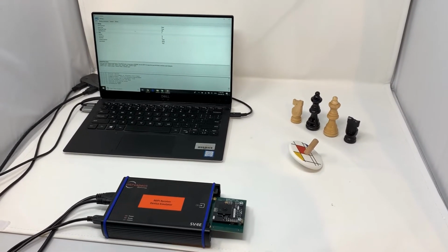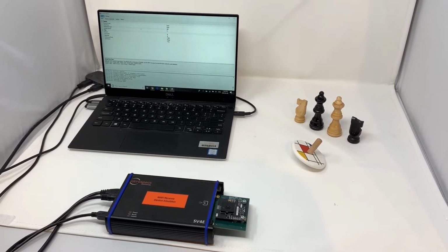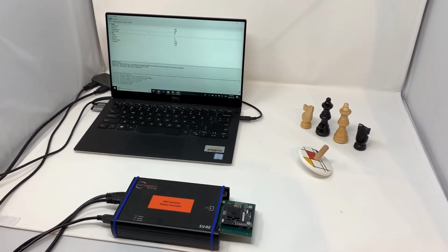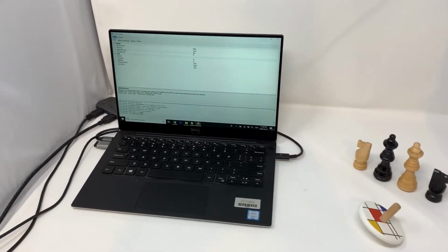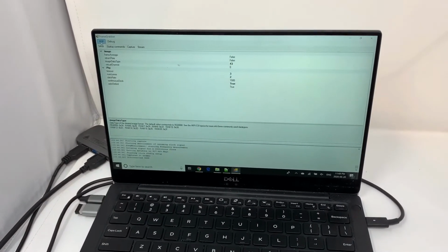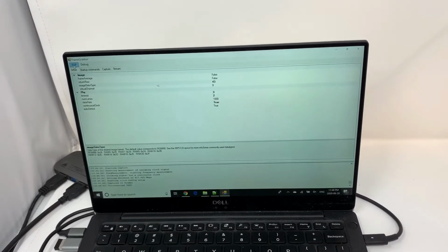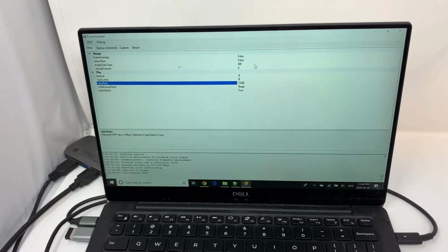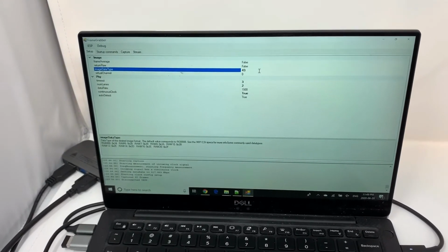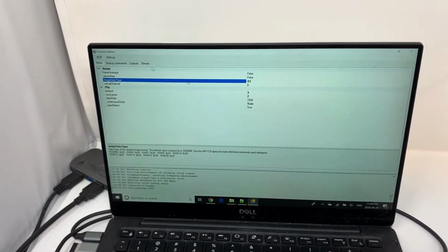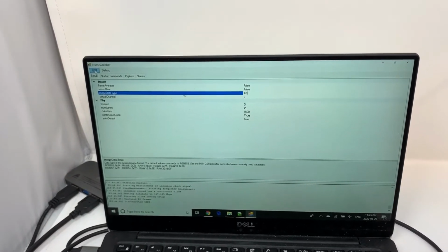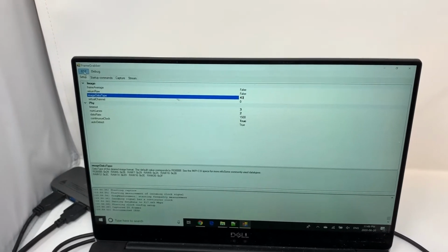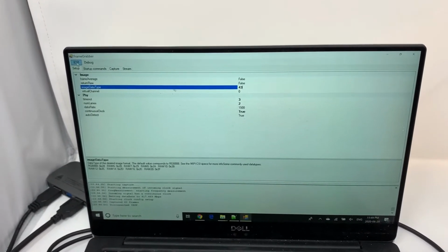To begin, let's take a look at the power-up and initialization of this camera in Introspect software. The image sensor on the SV4E can be configured with easy-to-use settings. In this case, I'll use auto detect for the data rate. The default is 1.5 gigabits per second, and I'll set the format in the image data type to RAW10. The SV4E supports all CSI-2 data types and pixel formats. The parameters shown here are just a subset of the configurations the SV4E can support.